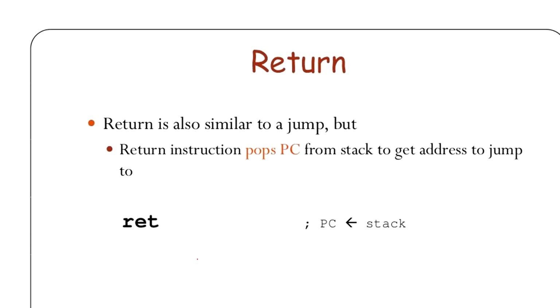Once your program, what you wrote in the subroutine, is executed, it comes back to the main program by the RET instruction, the return instruction. So return works as simply as a jump instruction to the main program where you called from. It is different from the jump instructions.